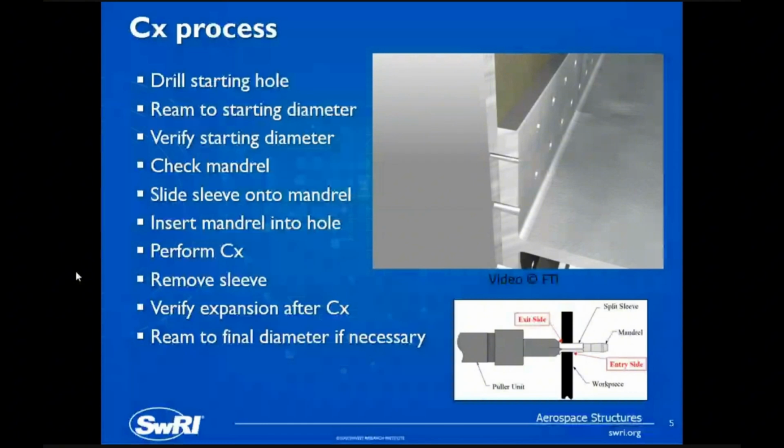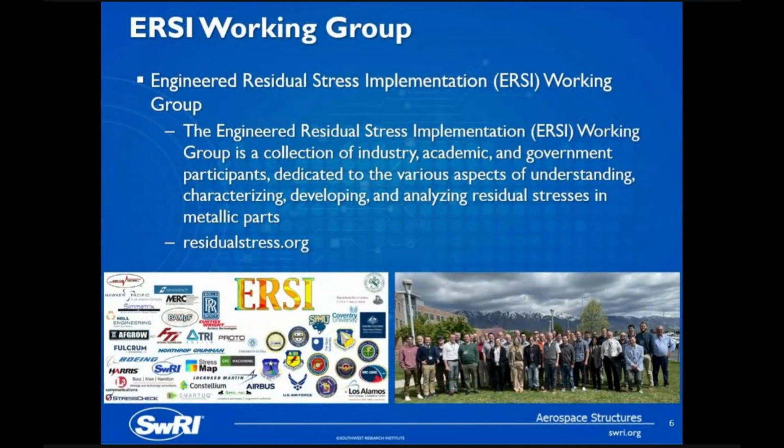So the benefit of that, like I said, it gives you much longer fatigue life on your critical holes in the structure. The problem for us as engineers is it makes the determination of the life of that crack quite a bit more complicated. And so the Air Force for a long time has used a fairly simplistic method to account for this. They essentially just make the initial flaw size smaller, and that gives you a longer life. But that can be fairly inaccurate depending on the differences in the geometry and material that you're working with.